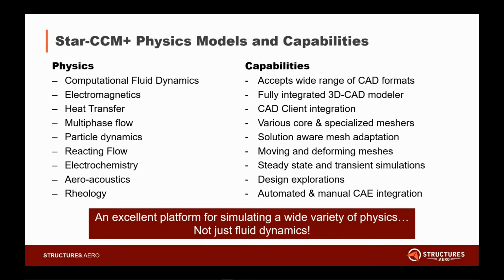Another big thing, I think, that's a new wave in CFD is solution-aware mesh adaptation, where you don't want to make a super refined mesh throughout the entire model because it'll blow up your runtimes. Instead, after a couple of iterations during the solution, STAR-CCM will reevaluate the mesh and say, okay, I don't need it to be super fine here, but it looks like there's a shock here, so let me refine this region so I can more accurately capture that.